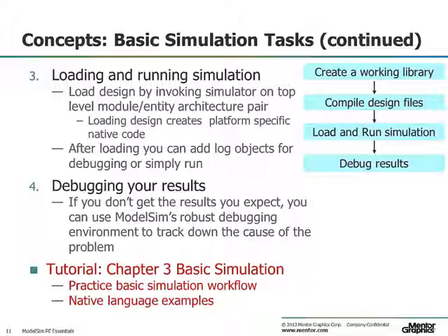ModelSim, the command name vsim, generates native x86 code when loading the design. We have a significant investment in ensuring the native code generation is optimized for the operating system and microprocessor's machine code. Once you have loaded the design, you can begin to stimulate the design with your test bench or through command line stimulus, or both.